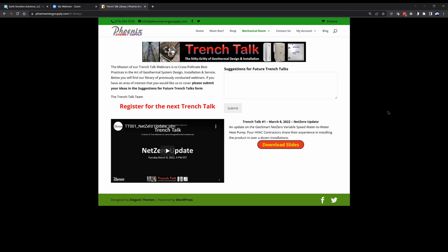Now, it's an identical valve, but with a transition reducing fitting to allow you to connect a 1-inch pipe to it, but that sudden drop in diameter needs to be factored into the pressure drop of the valve. I would say the 3/4 or the 1-inch are both perfectly fine on a 2-ton system. But it's interesting to note that the 3/4 inch has better flow characteristics than the 1-inch, strictly because of the sudden reduction in diameter at the entry and the exit of the valve.